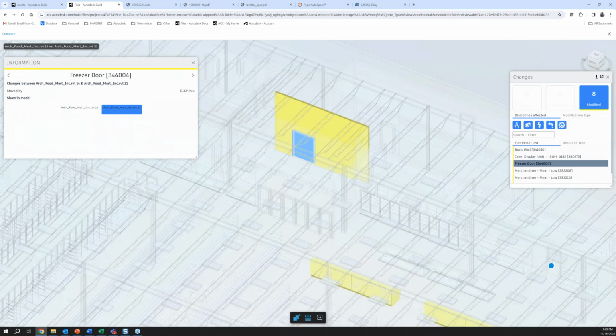If you're doing coordination review, if you're managing the VDC end and running coordination collaboration meetings, when you're picking up mistakes in the model and assigning issues, in the next meeting, if they say they're resolved, all right, let's make sure that you actually resolved it in the model. Let's check the old version that was published against the new version. All right, these are deemed closed.